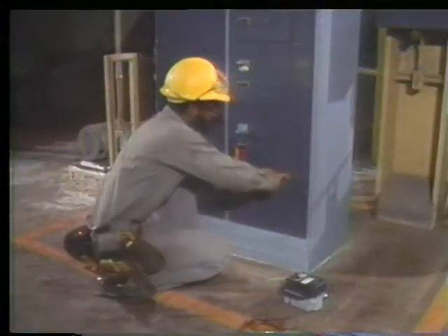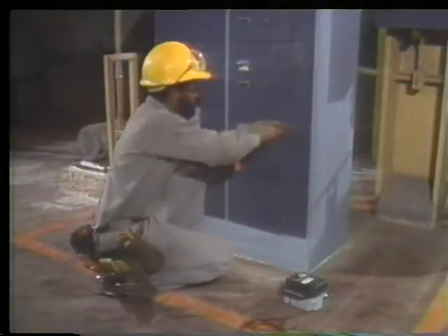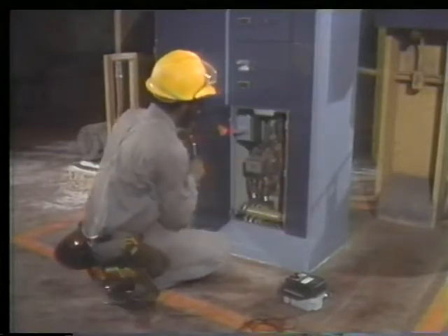The most common preventive maintenance test for a 3-phase motor is the insulation test. For this, a high-range ohm meter known as a megohm meter is used. First, make sure the motor is tagged out according to plant procedures. It's always a good idea to verify that the motor is really de-energized and that there's no residual charge on the motor. Then, it's disconnected at the motor starter or at the connection point at the motor.